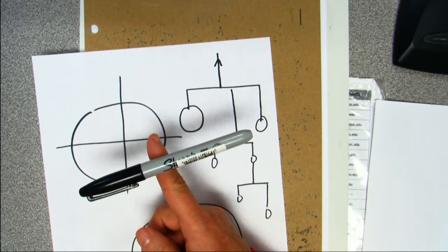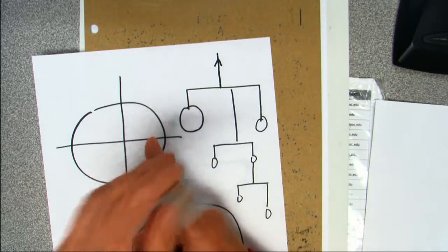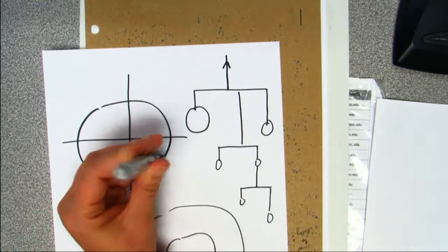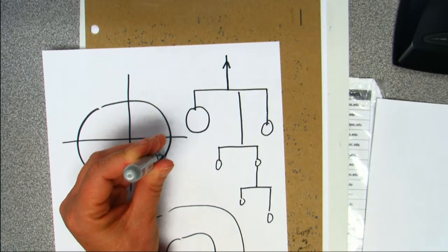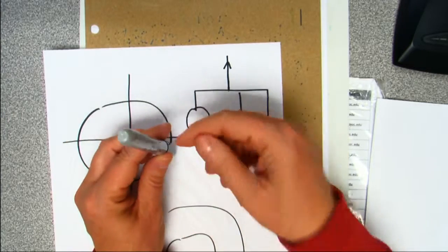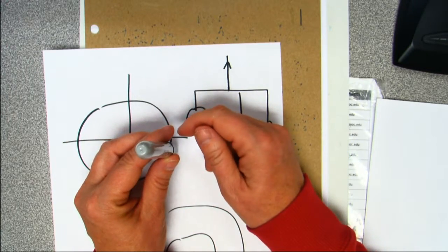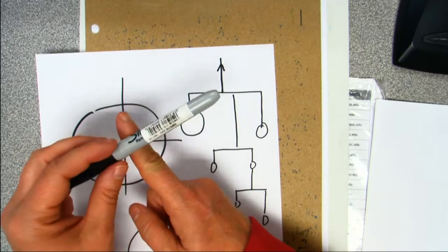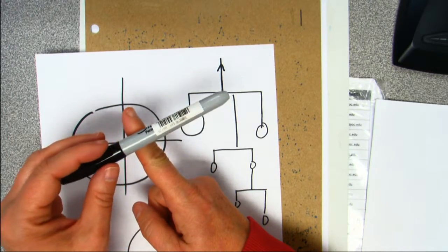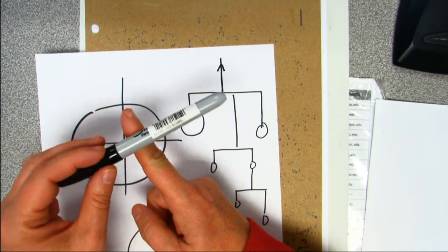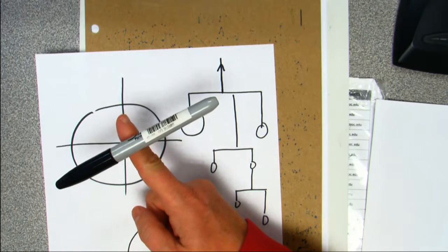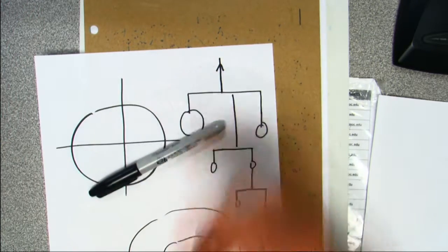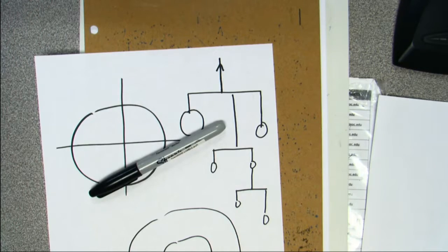We also know where the center of mass is for the other two coordinates, because this is symmetric, it's going to be on the axis of symmetry of the device. And because this is also symmetric, we know it's going to be halfway through the pin. So I can actually pinpoint, pun intended, where the center of mass is on all three, the X, Y, and Z directions.